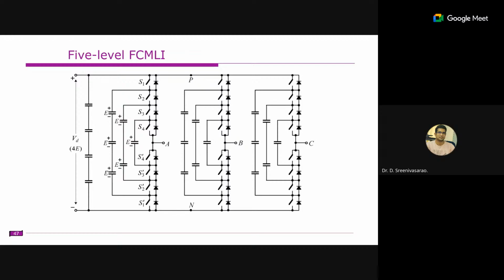This is another thing, which is the flying capacitor multi-level inverter. This is much less popular, but a hybridization of this one has some applications in the traction drive. It consists of some pre-charged capacitors. Right, these are some pre-charged capacitors here. These capacitors produce some voltage levels, and this is especially advantageous in applications like traction applications.